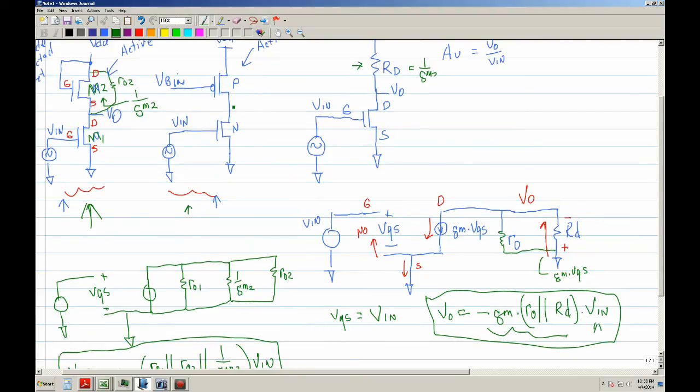On this one, it's a little bit different in that this is a P channel. So this is actually the source, that's the gate, and this is the drain. What you want to do is look at the impedance, and you typically put Z, meaning impedance, looking into the drain of that.